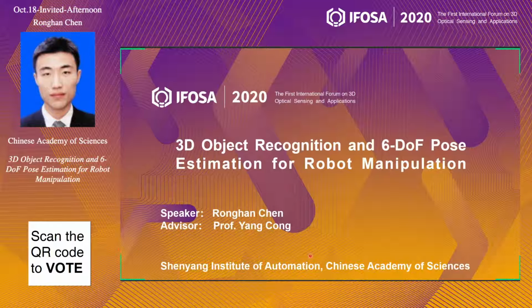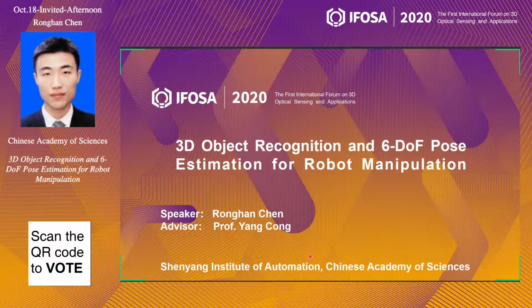So here we'll introduce some mathematical representations for pose. The location is often represented as a 3D vector x, y, z. Thus, it is 3 degrees of freedom, and the orientation is also 3 degrees of freedom and can be represented as theta x, theta y, theta z, which are the rotation angles relative to axes x, y, z here. Besides, there are also other representations, such as axis and angle.